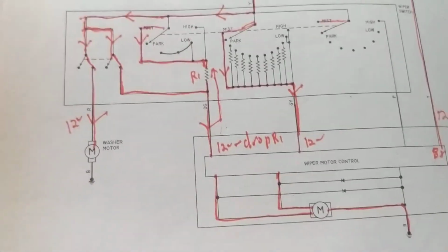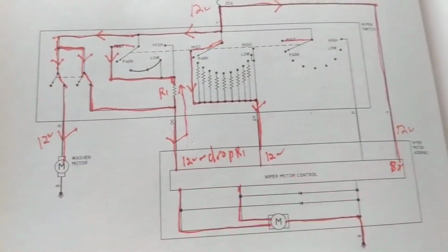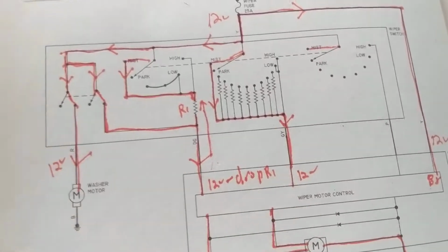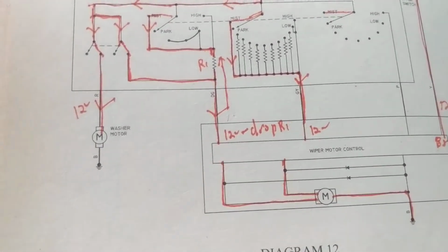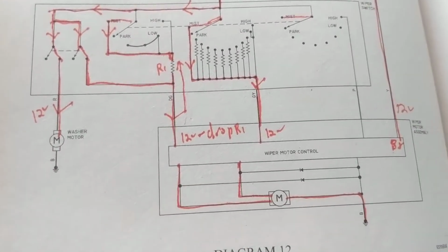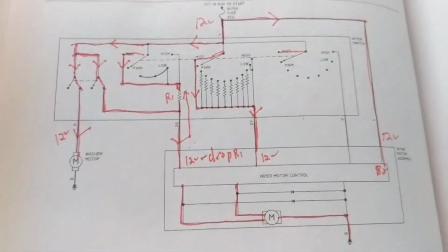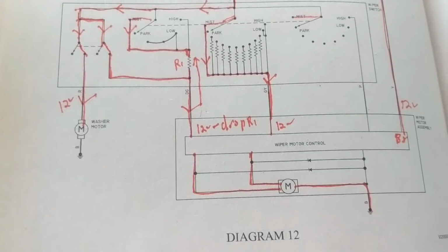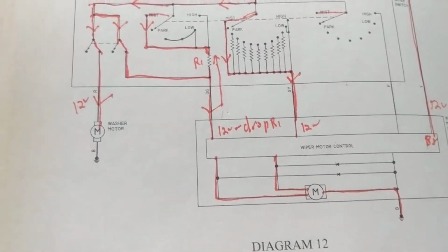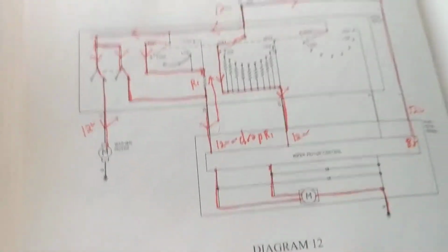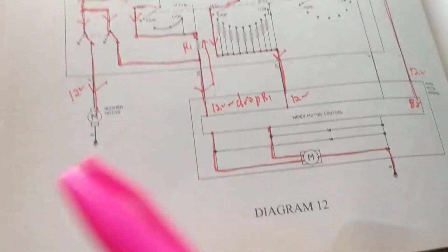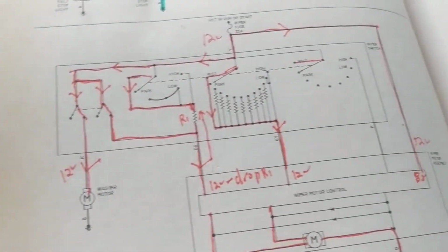Let's troubleshoot. Now, as I said, I want to spray a mist. I activate the switch for the mist, for washer fluid. Besides the obvious, that there is washer fluid in the tank, in the container, we check that. However, I don't hear anything. I don't hear the motor being activated.